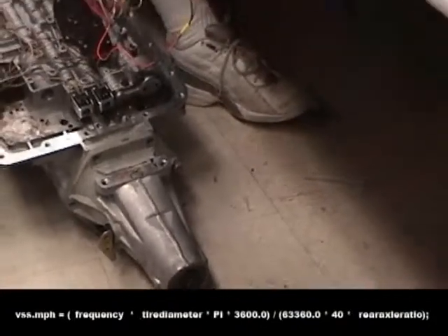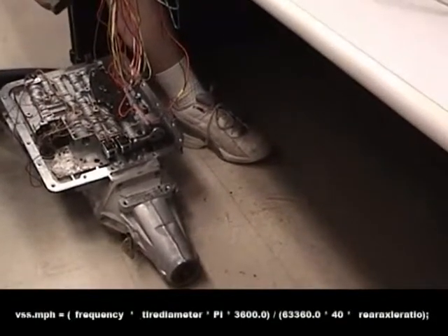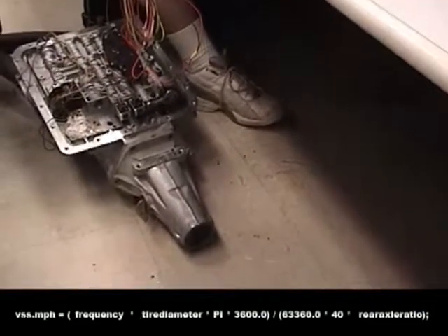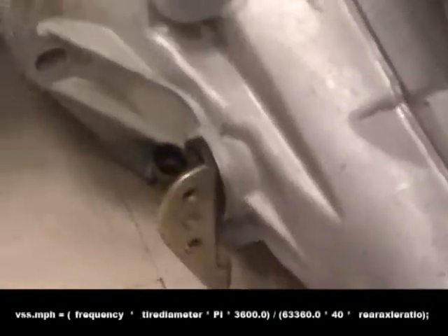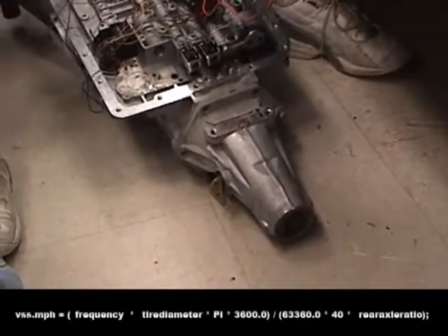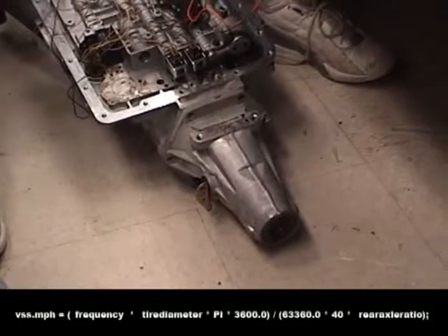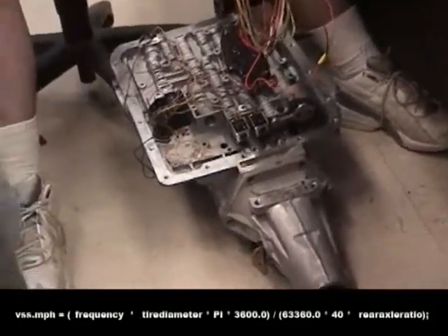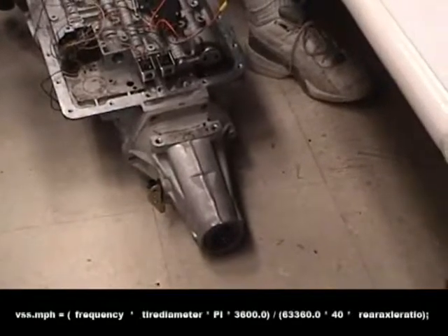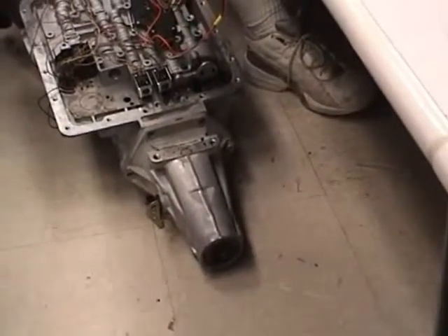The tail shaft is tied to the rear axle through your rear gear. So if you have like a 4.11 gear in the back of your truck, that means the drive shaft is going to have to make 4.1 revolutions per revolution of the rear axle. That way you're able to convert a whole lot of turning into more power and slower turning, so you can get a lot of power to the rear tire.